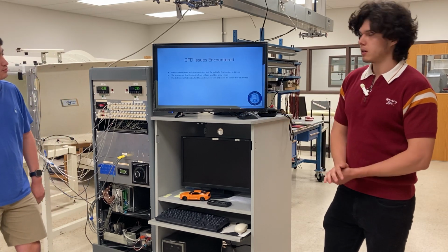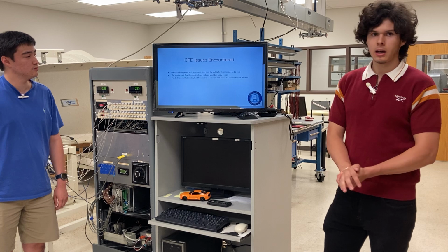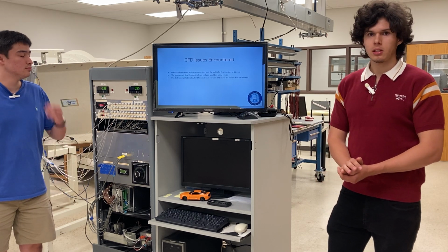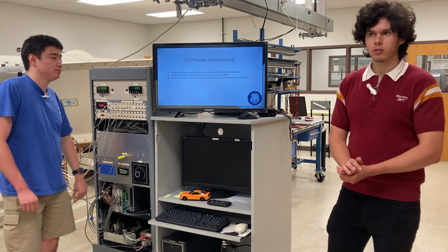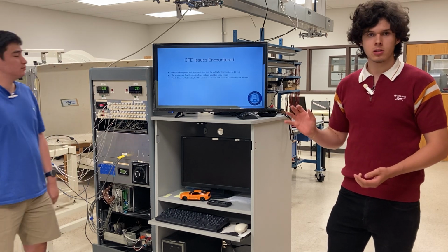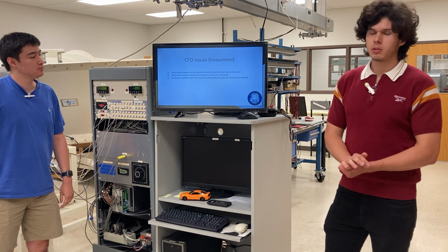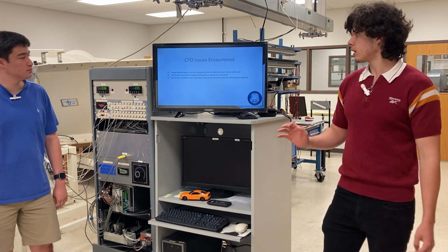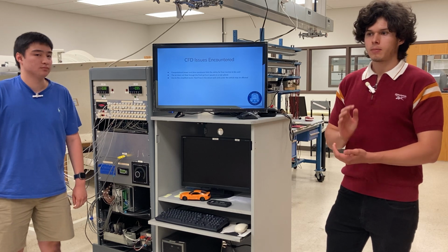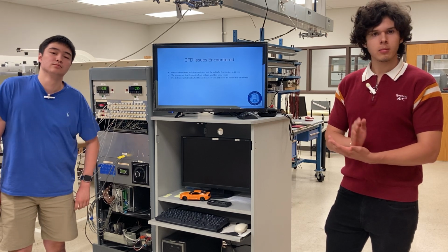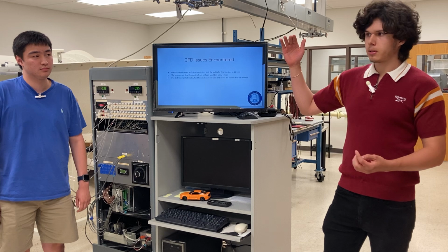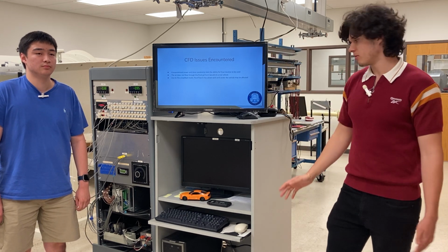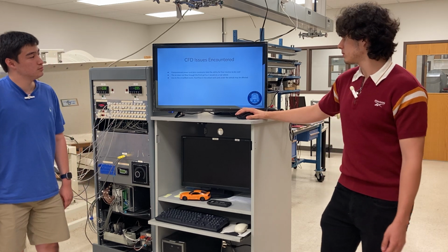So, as I was saying, regarding the CFD issues encountered, besides having to use a simpler model, the computational power and time constraints limited our ability to use a lot of precision. We tried to simulate with a higher refined mesh, and instead of taking, say, 20 minutes like our models took, it bumped up to 9 hours, which for calculating 16 different models couldn't have been possible.